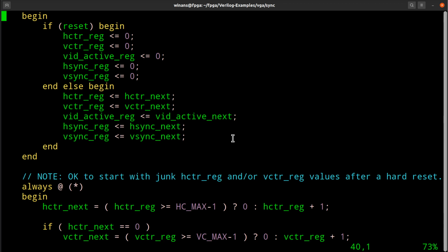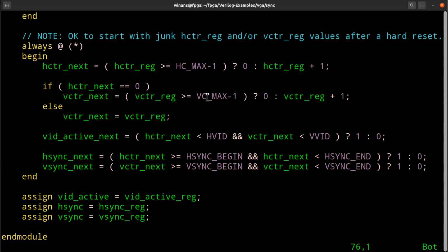And then I would go from there and look at the horizontal syncs after the vertical sync and determine the number of rows and columns based on the time between the horizontal sync pulses, okay? And then I would scale it and put it on my LCD. So my point is, it doesn't matter where we start the video. The monitor will eventually figure it out.